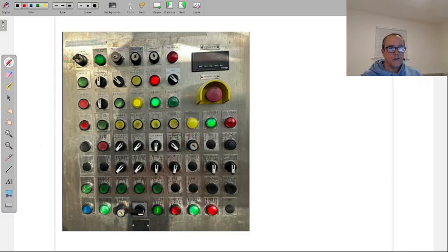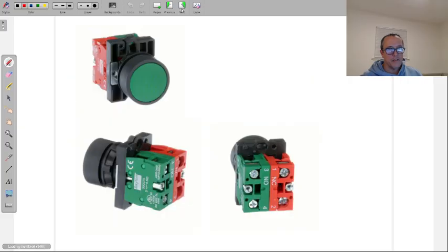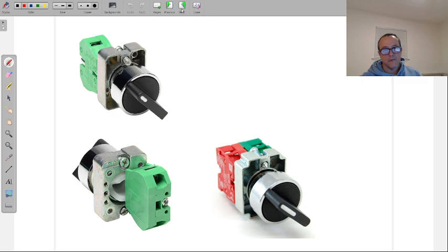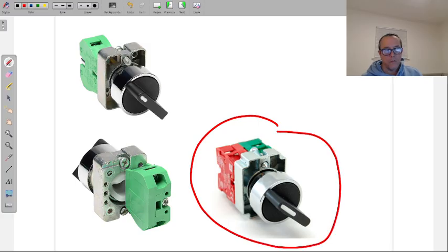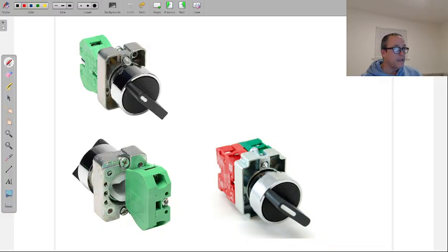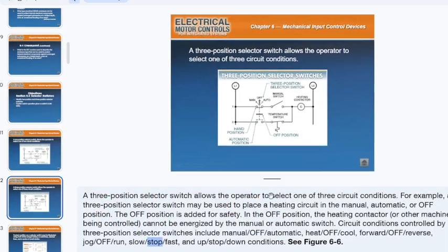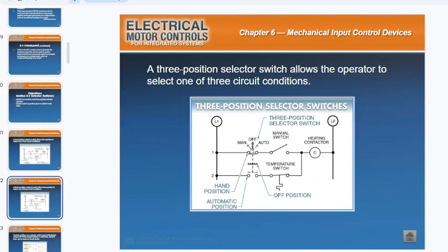These allow you to not only put the machine into the off position, but also to lock it into the off position, the auto position, or the manual position. It just doesn't allow anybody to change that position. And almost in all cases, the two position doesn't have to have a second contact. It can just be the lack of one contact. But almost in all conditions with selector switches, since you have a normally open and a normally closed function, that's what we're looking at here. If you look at the symbol of this switch, one is open while one is closed.